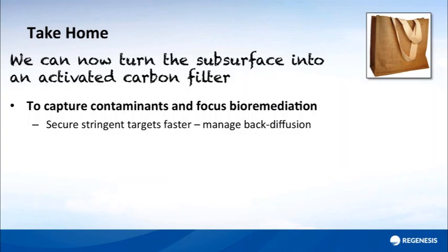This is qualitatively different from many cleanup technologies which work well at moderate contaminant concentration levels but tend to have an efficiency which tails off as the concentration drops. PlumeStop is the other way around. It has moderate efficacy in medium concentration ranges, but increasingly great efficiency as the concentration goes down. It makes it particularly useful as a tool in a treatment train approach if starting concentrations are that high.